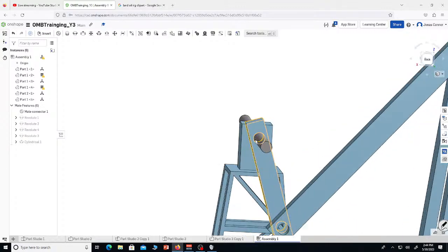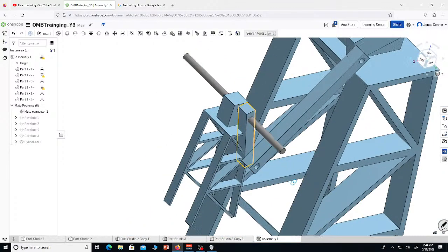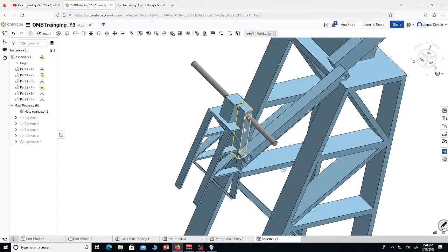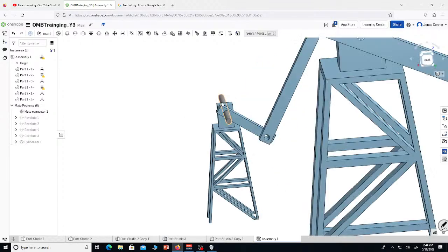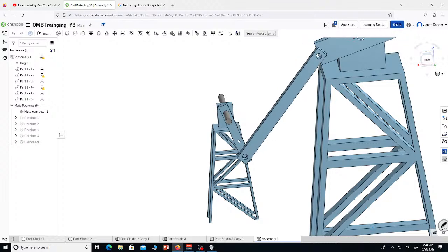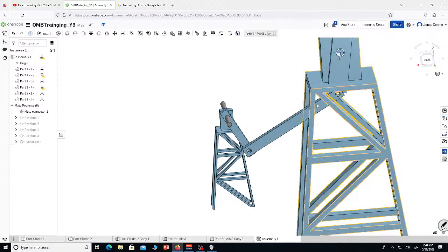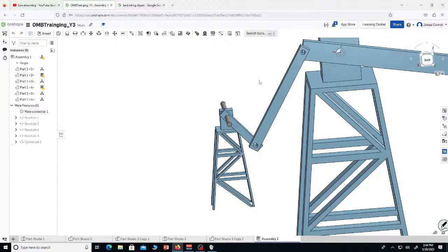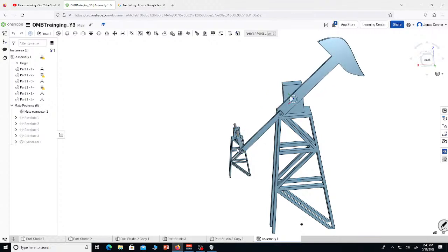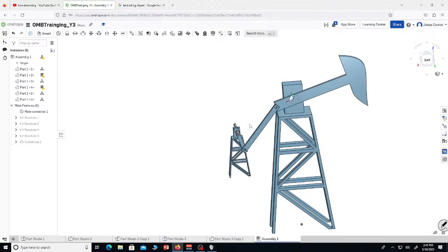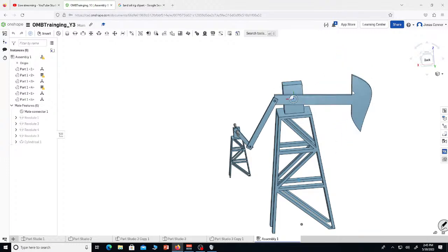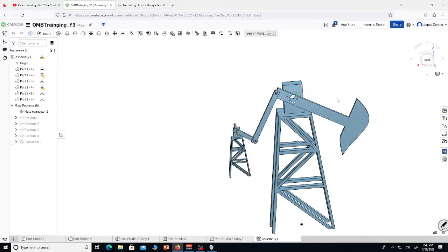So if we were to hook a motor up to this right here, and then, you know what? These parts you could easily 3D print and make a model of if you wanted to demonstrate that. So all we would have to do is attach a motor right here and just move this like the tiniest bit. So you see it only moves just a tiny amount, but it moves that a whole lot. So there's a whole lot of torque in what would be this motor, but very little movement. So I'd have to have a really high torque gearbox to be able to move this properly. So you can kind of see the fruits of our labor, kind of how that works.